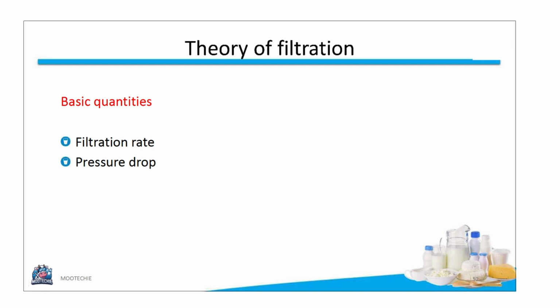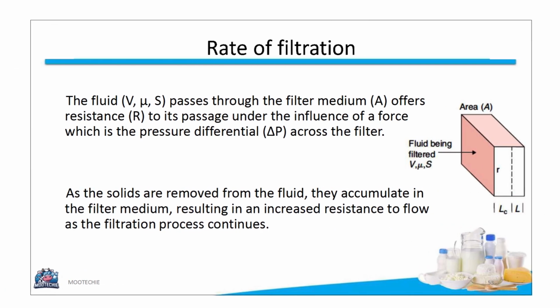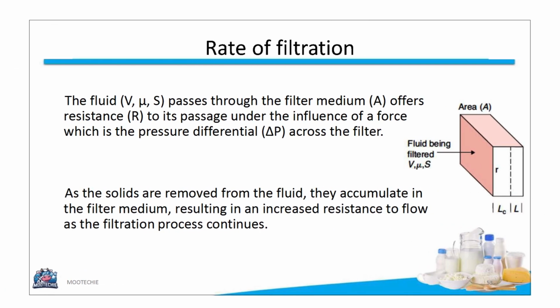The theory of filtration revolves around two basic quantities, the filtration rate and the pressure drop across the filter. The rate of filtration depends on the fluid properties, volume V, viscosity μ, and solids content S, passing through the filter medium of area A. The flow experiences a resistance R and is driven by a pressure differential delta P. As solids are removed and accumulate, the resistance to flow increases throughout the process.